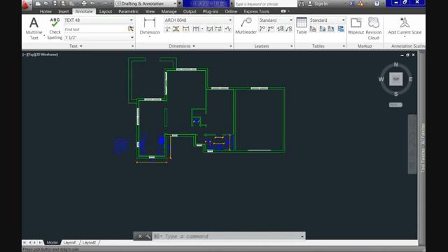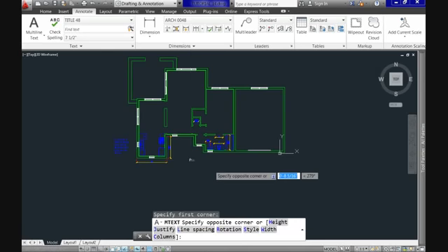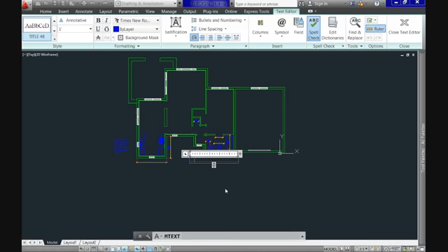And finally, let's use our new styles by calling the title 48 style. Now use the multi-text command and let's write floor plan and center it below our plan as a title for our floor plan. Now let's do the same but with the dimension styles.